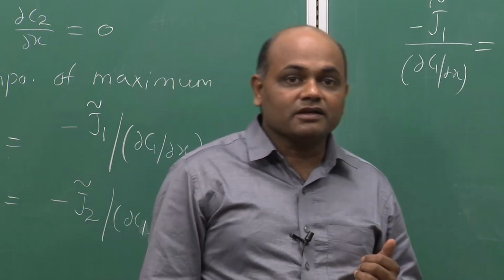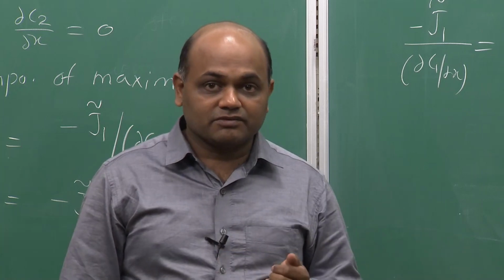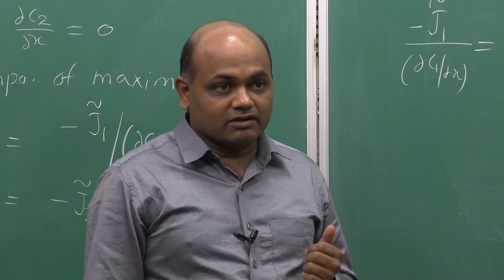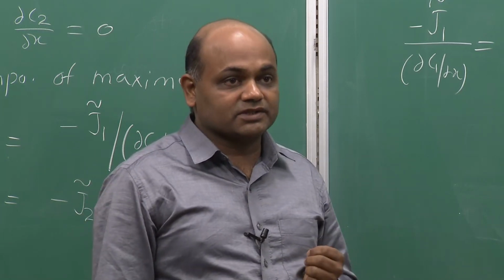Again, it will not be an entire set, because in quaternary, for example, we need 9 interdiffusion coefficients, and so through pseudo ternary couples, we will get 4 out of the 9 coefficients.